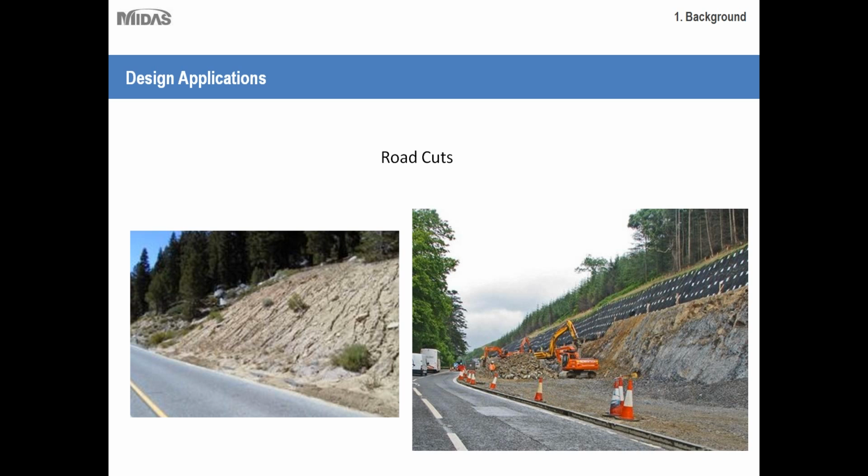So that's just another thing you have to keep in mind as an engineer: depending on the project conditions you have, you might have to create certain fail-safes just in case the slope does fail. Because the slope is very high and very steep, the engineers felt that the design required several fail-safes or design precautions just in case the slope did fail. Whereas with maybe more stable materials, you don't really have to worry about those precautions. So once again, road cuts would be just another example of design applications for slopes. I'm sure you've seen them around.